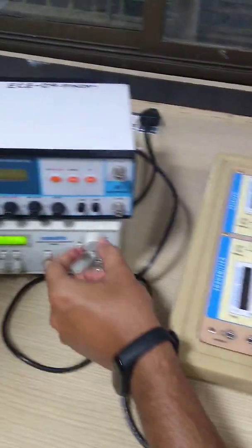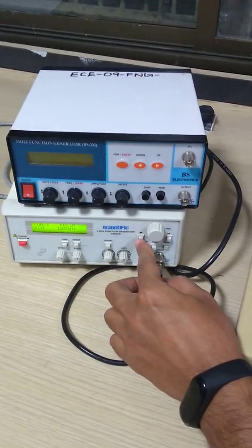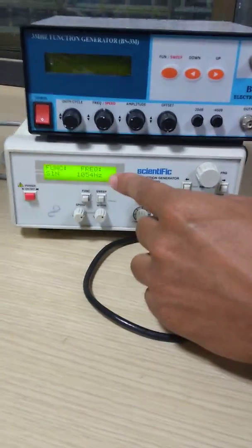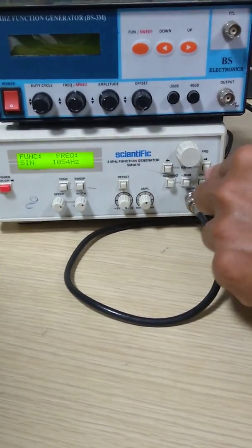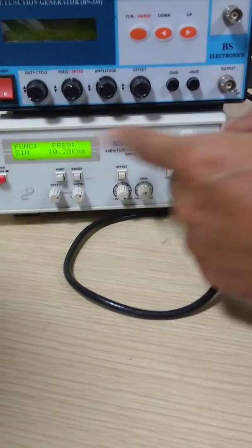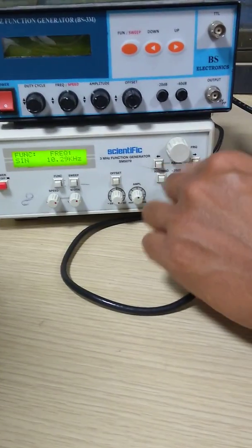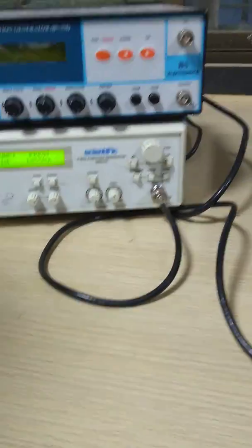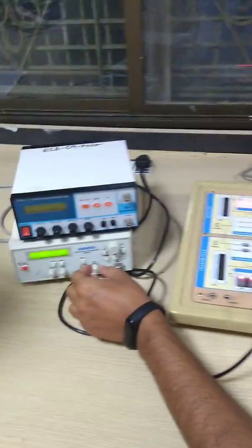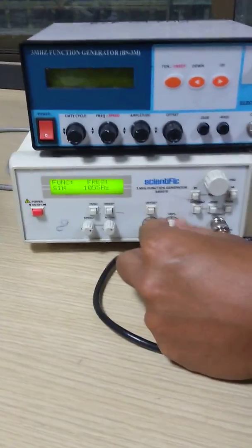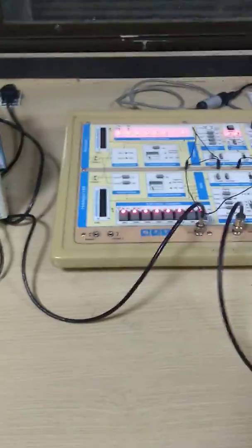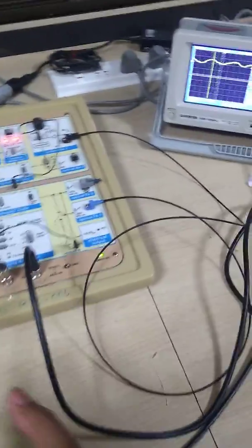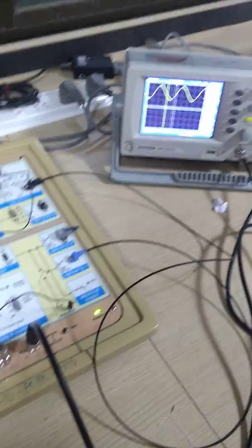If it's not set initially, this is to vary the frequency, as you all know, and this is to vary the decimal points. For example, if we are at 1000 hertz and we want to go to 1 kilohertz, instead of just rotating it, you can just go like this and you are at 10 kilohertz right now. So to change the decimal places, you use these two keys. And if you don't have a 1 volt signal over there, you change the amplitude using this knob till you get 1 volt. After you have set the signals, that's done for that part, and you have your input signal over there. Now these cables can be sensitive sometimes, so take care of that.